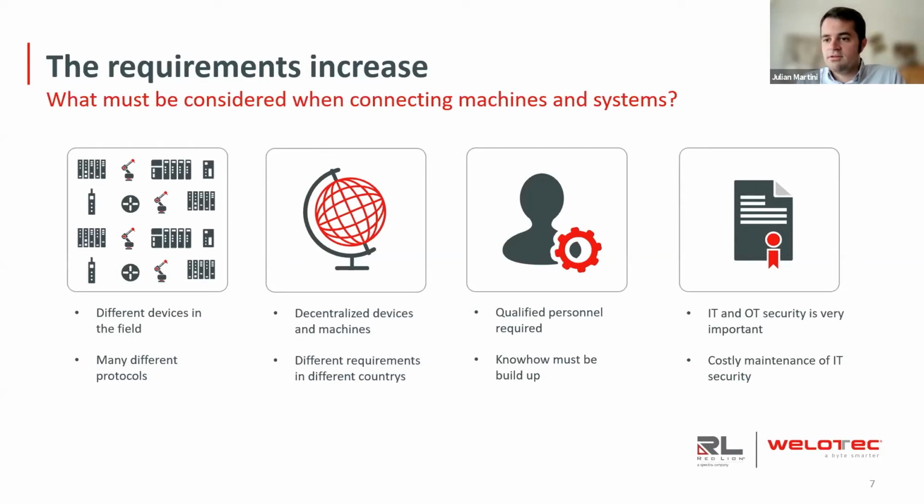There are various choices to be made. For instance, you could opt for OPC UA or MQTT. When you do so, you might want to have a look at how much data is being transmitted, because the bandwidth that you have is limited, and the more data you transmit, the more you might have to pay for it because it costs money, right? And then also how secure is that kind of transmission that you're opting for.